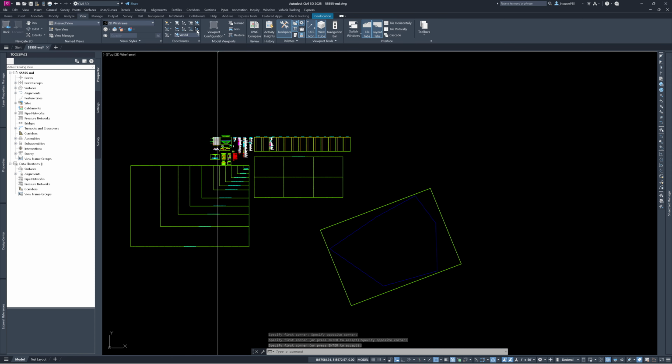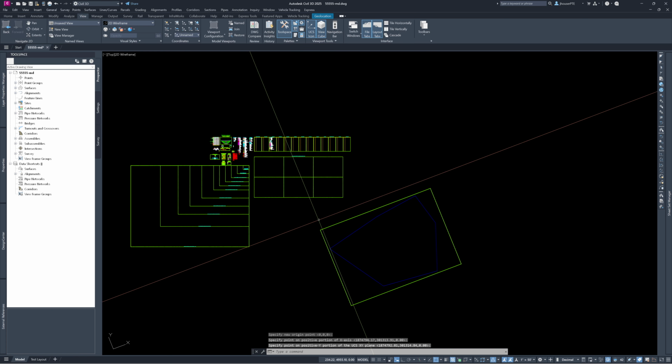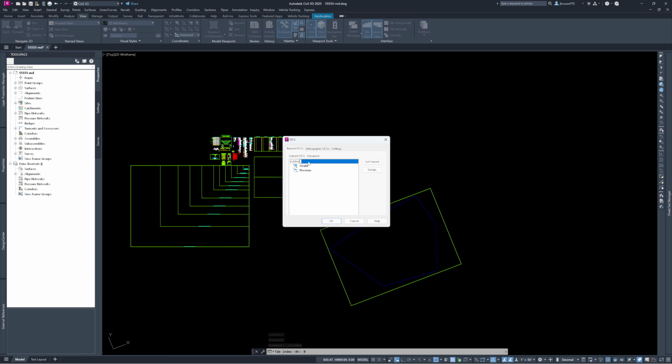So we'll change our rotation, set up a custom UCS. Make sure you rename that. Now, since I know this is a 200 scale, I'm going to put 200 on here because I have a feeling we'd have to break this down into smaller sheets and maybe a slightly different rotation in future. All right, so there's our rotated 200.